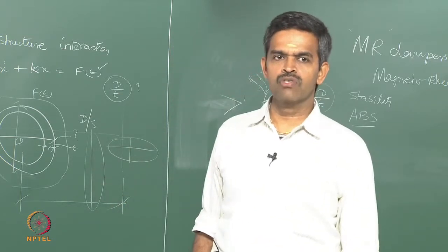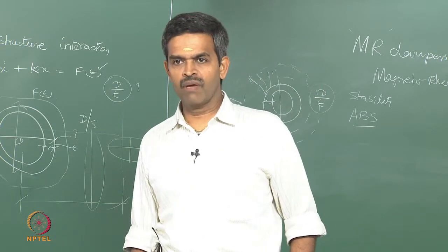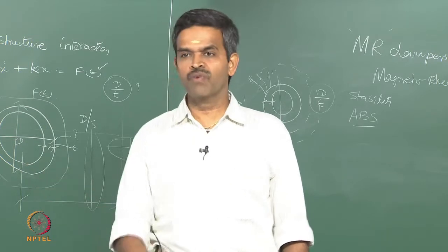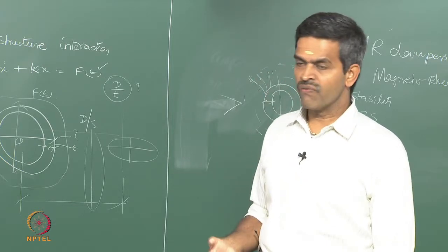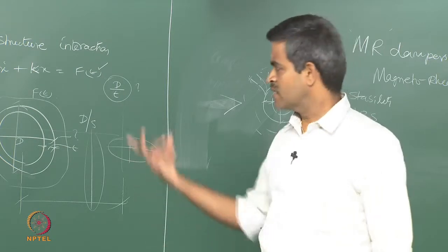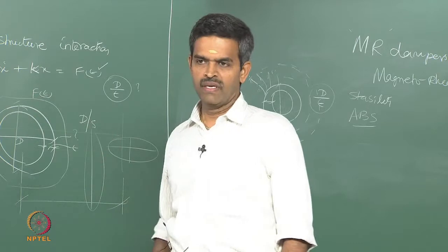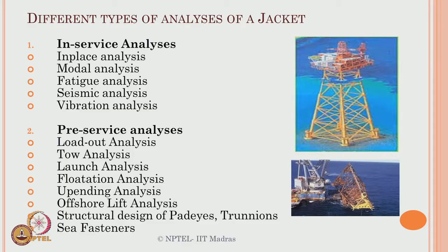Land-based, onshore structures do not have any complexity in pre-service analysis, because the complexity generally arises in installation and commissioning or decommissioning of an offshore platform compared to the design itself. The members may fail when they are being launched, towed, floated or upended. These are operational stages. In the installation of a jacket structure, the figure here shows one of the upending stages of the template leg.